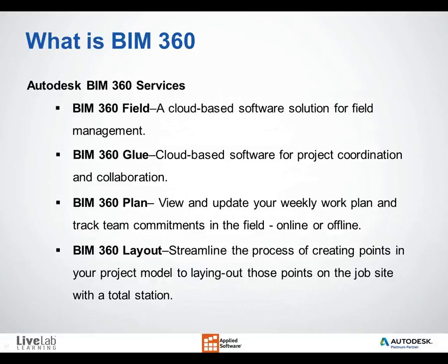BIM 360 Glue allows us to connect the entire project team and help streamline the project for review, collaboration, and coordination. This is where we're actually viewing a model, and we can do markups as well as clash detection and coordination.